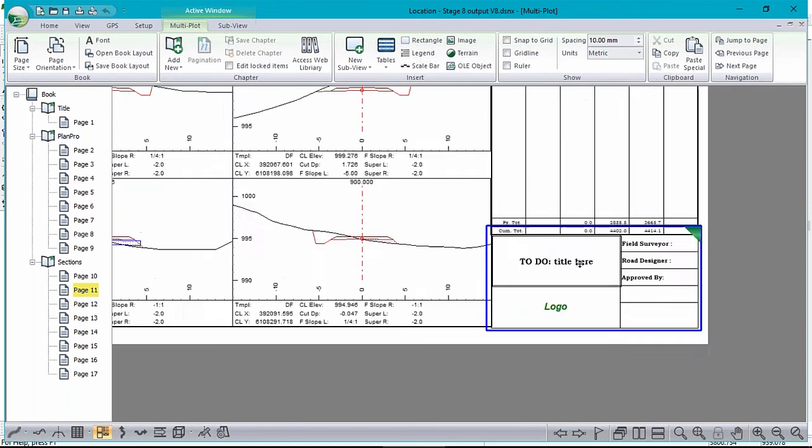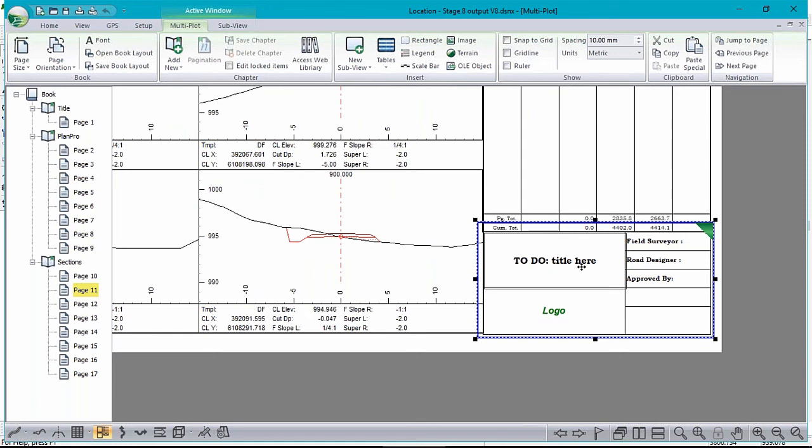Right, so I'm looking at this, and now I click here, and it's getting the wrong window. There's two ways to deal with that. I don't know how many of you are familiar with locking, but if you lock this rectangle, it'll never select, so you don't have to worry about getting it by mistake. If you need it to be unlocked for some reason, or if you've unlocked everything like that, then Control K shuffles it to the back, and now you can click on the other things in front of it.